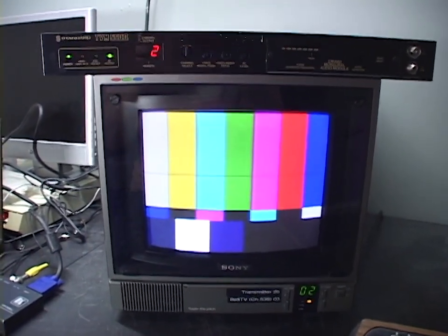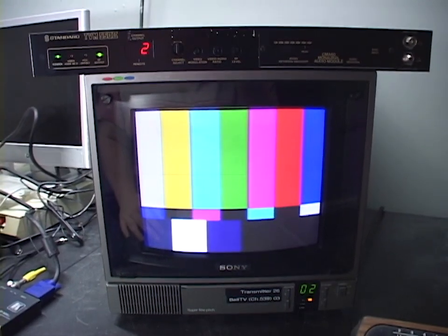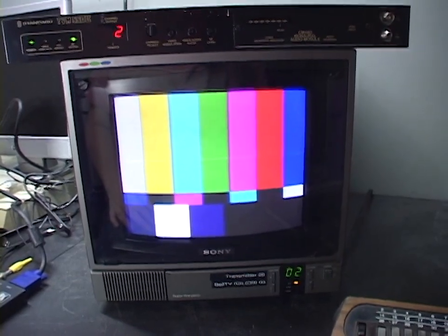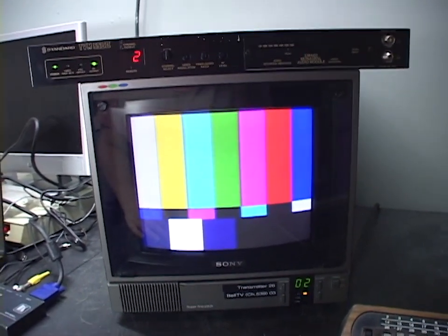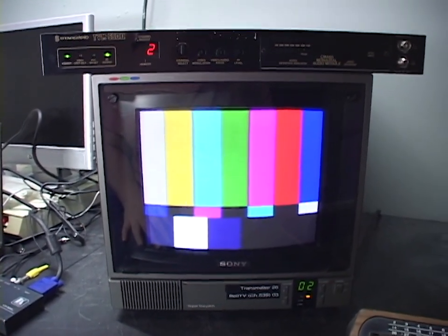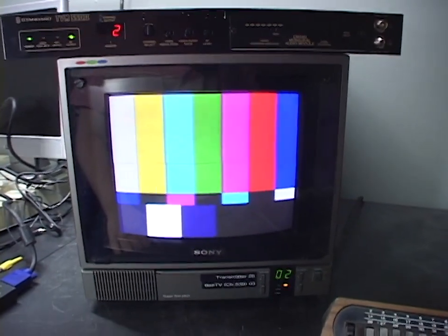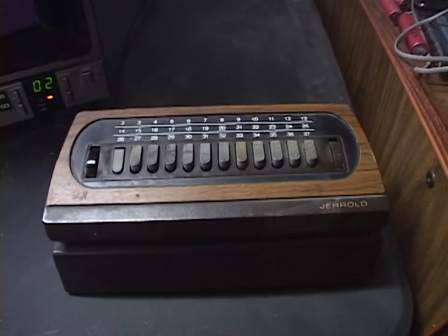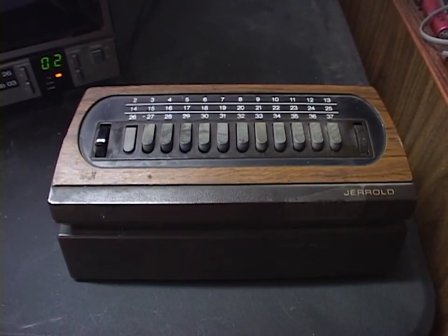So you'll notice so far that I haven't gone past channel 13 on this thing, and that's because for analog cable, only channels 2 to 13 match up with 2 to 13 on the broadcast television band. Once you get past that, the frequencies are totally different from broadcast television. So you need a cable tuner, which this TV doesn't have. But I can solve that. I have a cable tuner right here, and this is the second subject of this video.